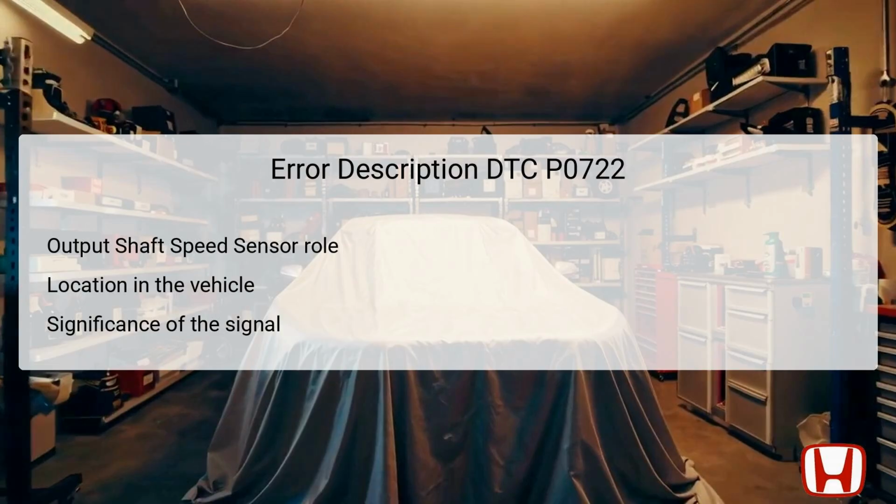DTC P0722 indicates a lack of signal from the output shaft speed sensor. This sensor is responsible for measuring the speed of the output shaft, which in turn informs the transmission control module about the transmission's operating conditions. The sensor is typically located on the transmission housing, specifically around the output shaft area. The data it provides is fundamental for the electronic control unit to make proper adjustments during gear shifts.